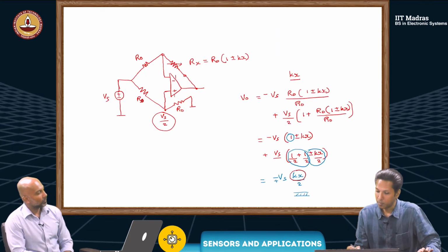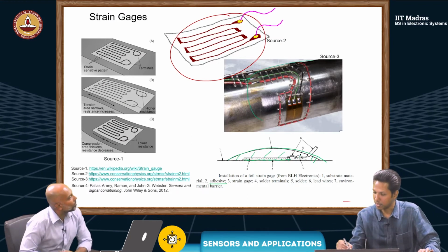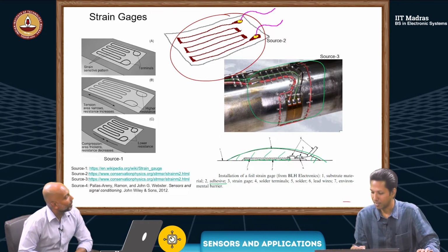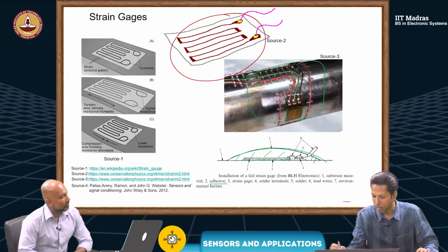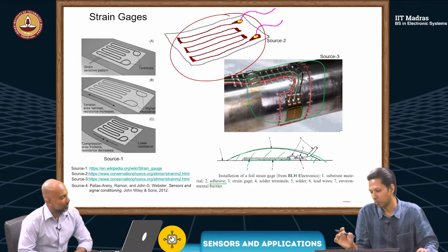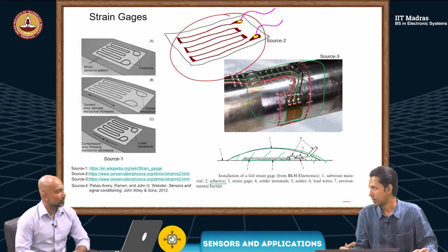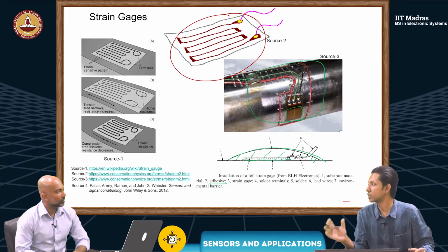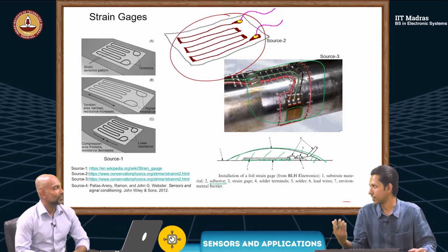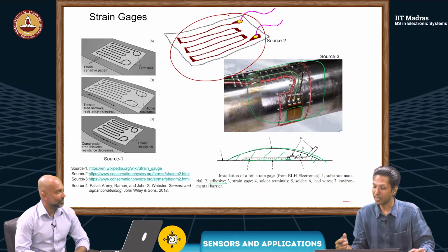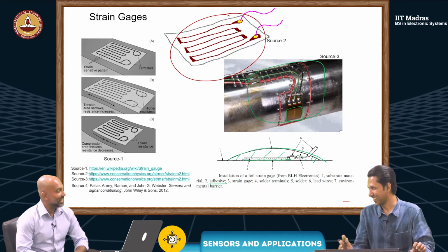Like we have seen in the previous photograph, you look at the structure here, such a big one. So that's the one carrying the load. And the strain gauge is such a small element, very thin. So it can freely expand and contract compared to the structure. If the structure undergoes strain, this will undergo strain as well. It just fetches that information. Like we mentioned, the strain gauge will not bear the load.